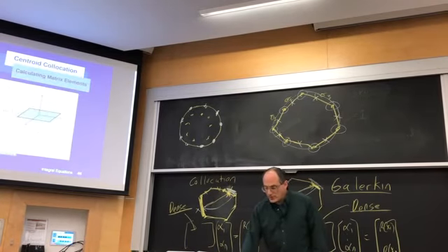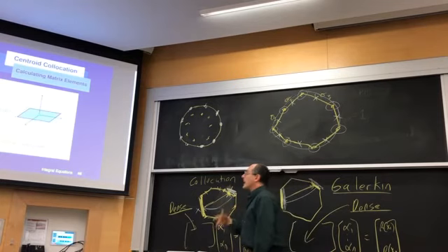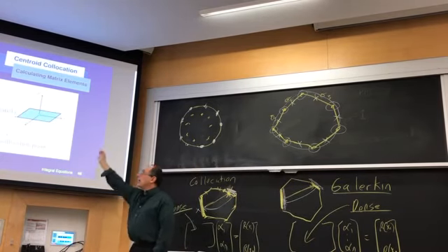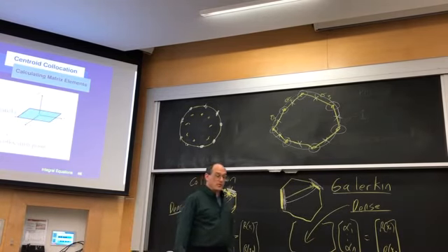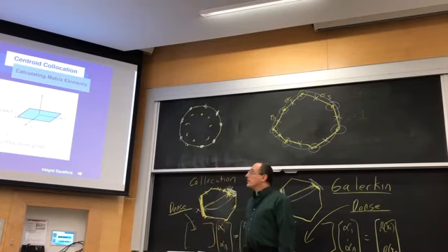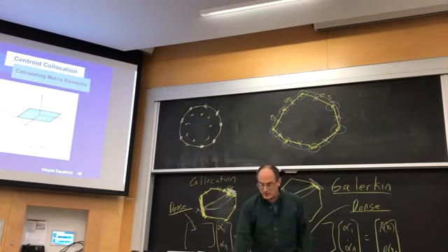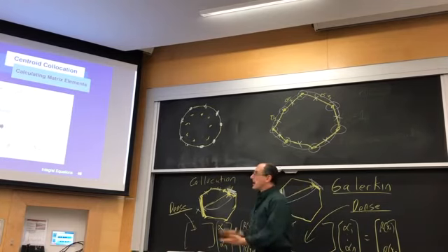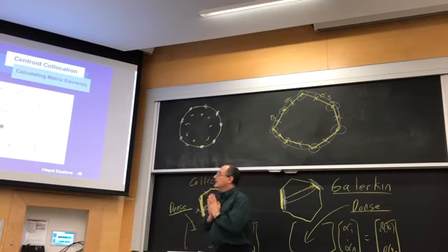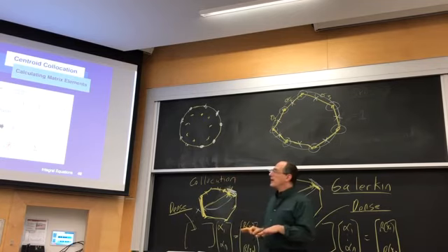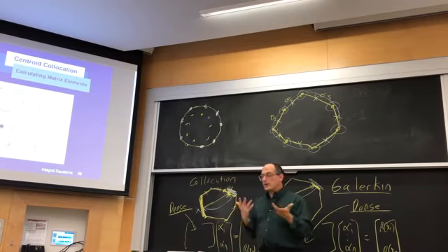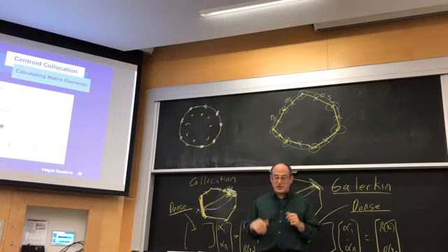And one of the difficulties is that you have to calculate this integral over a panel of this 1/r function and evaluate it at test points. And as long as the panel is here and the test point is here, that works fine. But if they get too close to each other, like if you want to calculate the potential on a particular panel, if you're close by, you can sort of break it up into 4 panels and do it that way, and treat it as point charges, so you can do approximations.